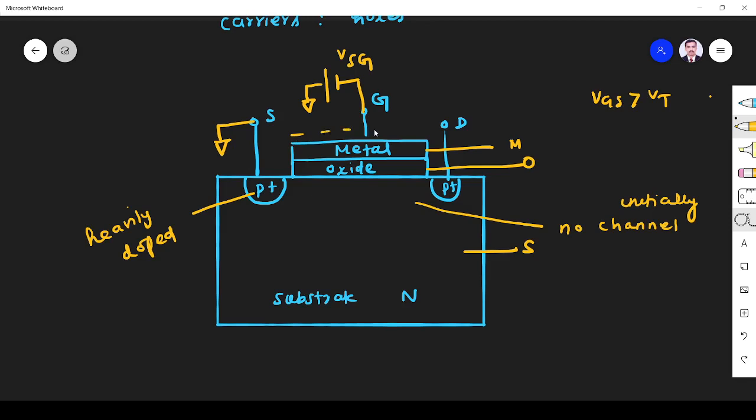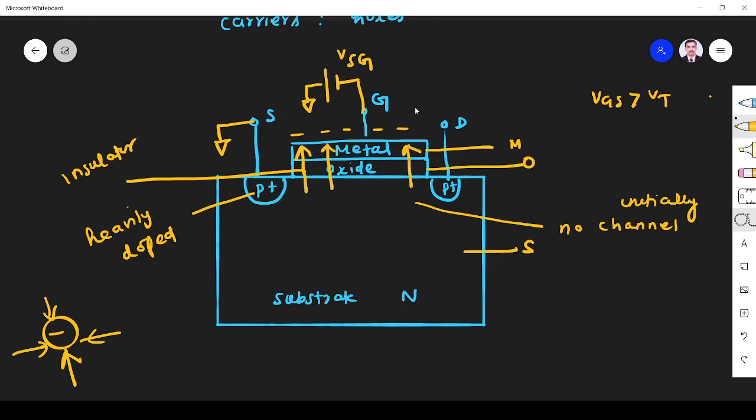The negative charge carriers accumulate here, right? So this will create an electric field. These charge carriers cannot flow through this because this oxide layer is an insulator. But these charge carriers can create an electric field because they are all static charge carriers. For a negative charge, the electric field will be like this. They are all coming towards the charge. The electric field can penetrate an insulator. That is not at all an issue, that we know from EMF theory.